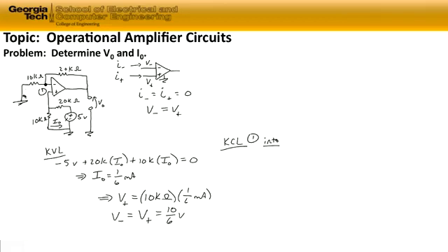It's going to be 0 volts minus the voltage here, which is 10/6 volts, divided by 10K. So 0 minus 10/6 divided by 10K. We also have the current which is flowing from right to left through the 20 kilo ohm resistor.